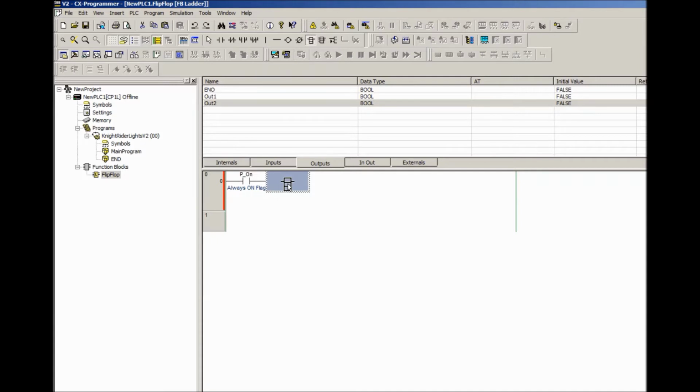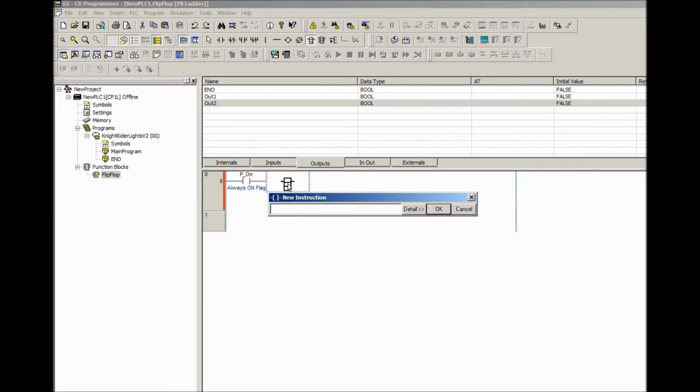So if I have a maximum value of 255, there will be 2.5 seconds in my delay, and that's too much. So the first thing I'm going to do is divide this by 5. And to do this, we're going to use the forward slash, that's a divider. We're going to divide the speed into 5, and the output will be in the temp value.